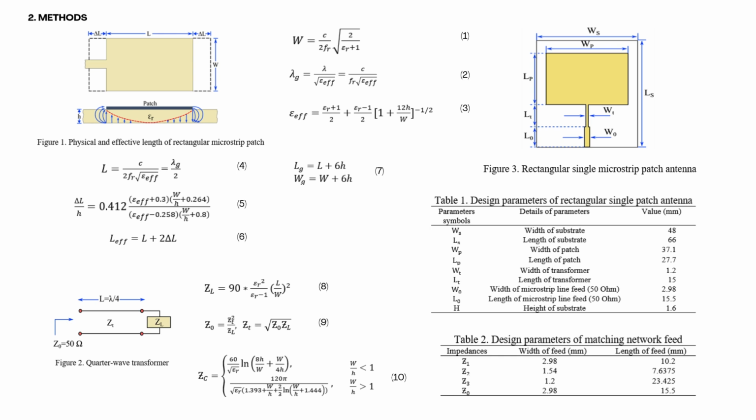In this article, the microstrip edge feed was favored for its design simplicity and ease of fabrication, which involves connecting a microstrip transmission line directly to the edge of the patch antenna. With any feeding technique, achieving accurate impedance matching is vital as it minimizes signal reflections and standing waves while maximizing the power transfer efficiency. Impedance matching flexibility can be achieved by varying the width and length of the transmission line.